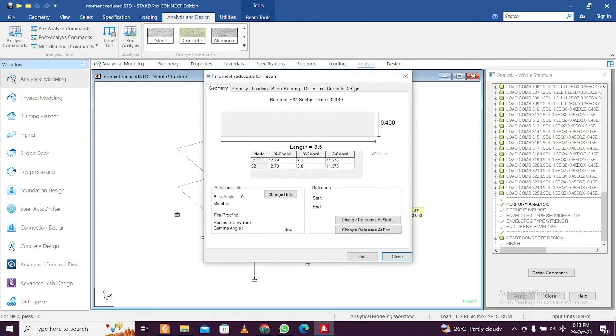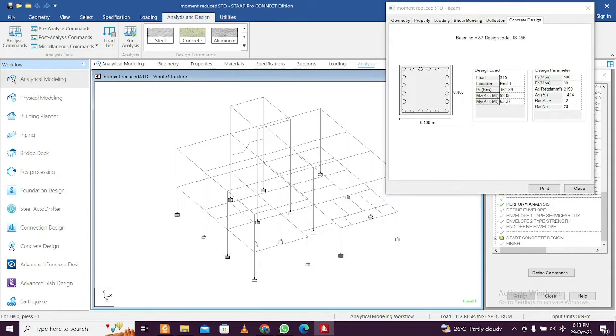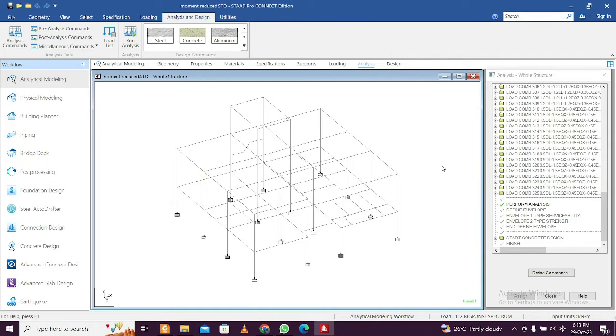If you double click on the building, obviously the complete design will be seen. Let's note down the AST for the left section, the first two digits. 1300 is this one, and then we have AST required 1900, and then 2700 and 2000. In this we haven't considered the correct beam moment of inertia given in the IS code. By default it is taken as 1.